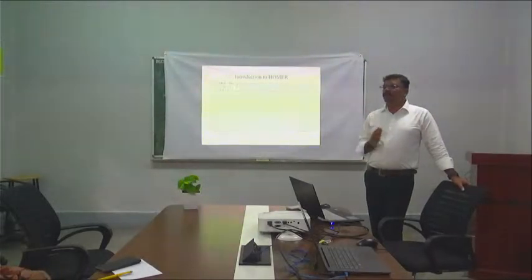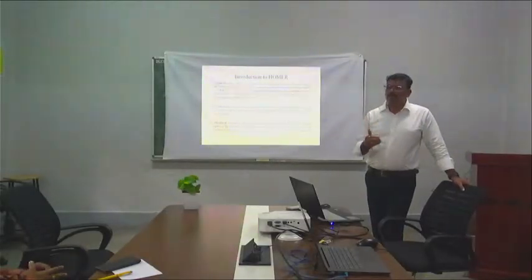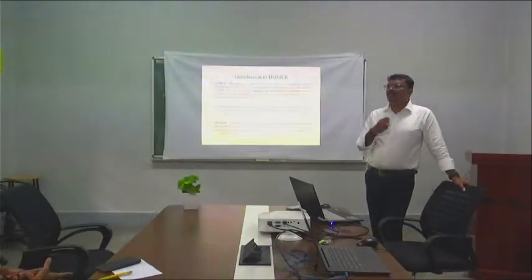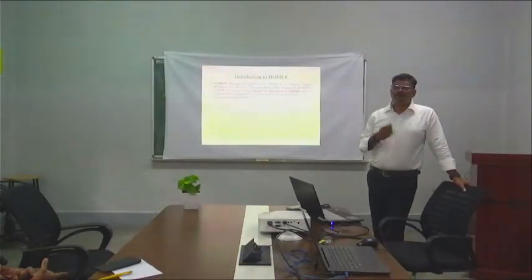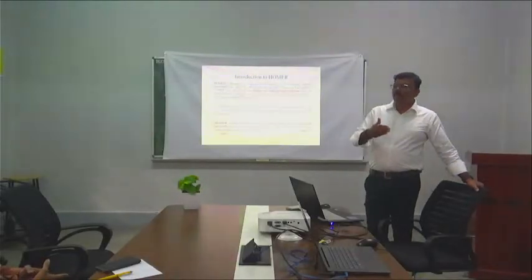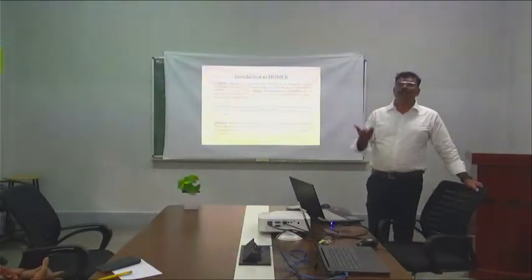Suppose I wanted to design a microgrid for Dayananda College. From where to start? What do I have to do first? First, I should understand the load characteristics of this Dayananda College of Engineering. That means, what is the load variation over 24 hours? What is the load variation quarterly, yearly, over 6 months?